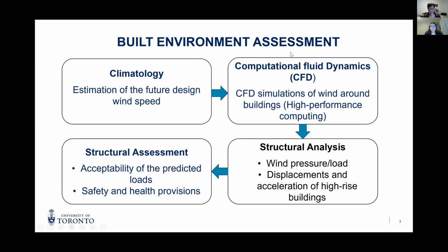And for the built environment assessment, we first start with the climatology. We estimate the future design wind speed based on some global climate models. And then we feed the data from those climate models to a smaller scale CFD model. From that, we can extract the structural load and evaluate some criteria based on structural analysis. And finally, we can check if they are at an acceptable level.